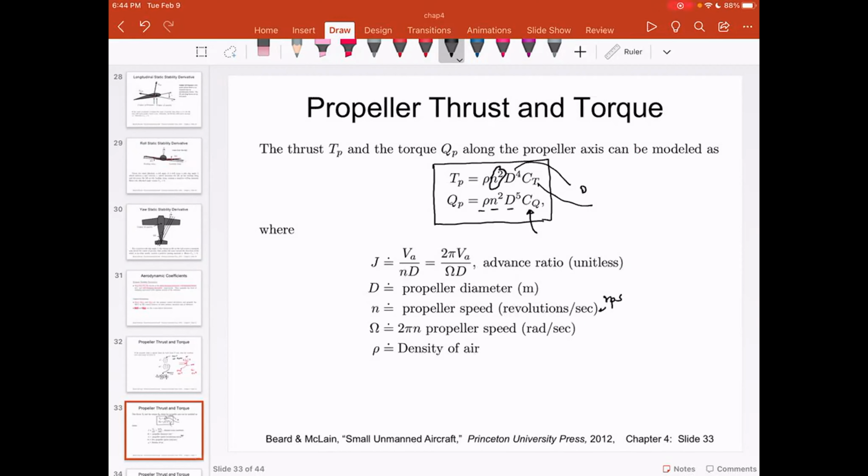If you look at some exotic airplane designs, where in certain cases the orientation or the prop angles could be changed at runtime, we are not going to look at that. In helicopters, you can change the angle of the prop using the swash plate, but not in fixed wing planes or UAVs that we are studying. So we will assume all prop geometry to be constant. Which means if I give you a prop, we know the value of Ct, and that Ct does not change.